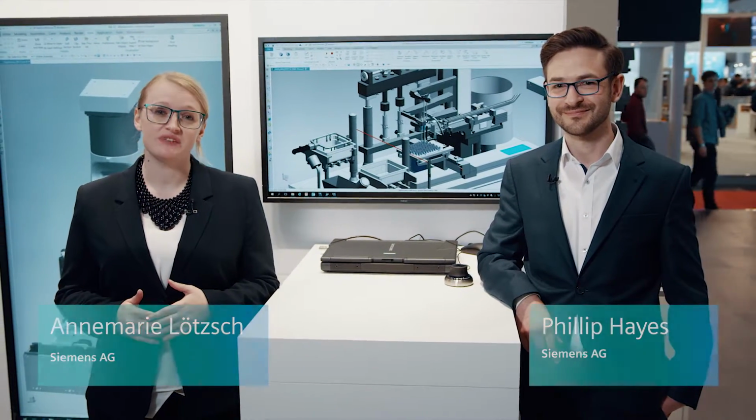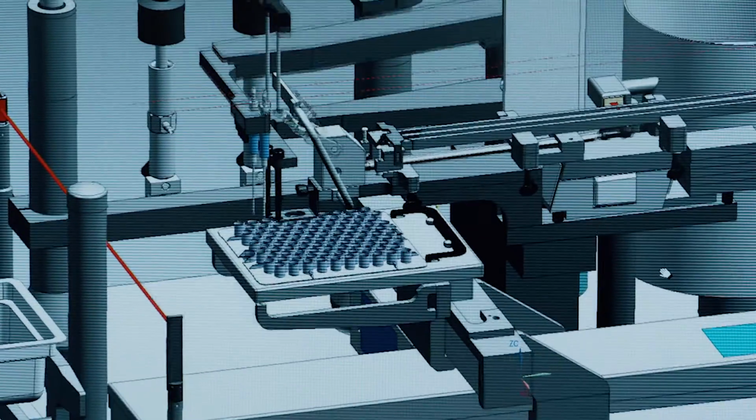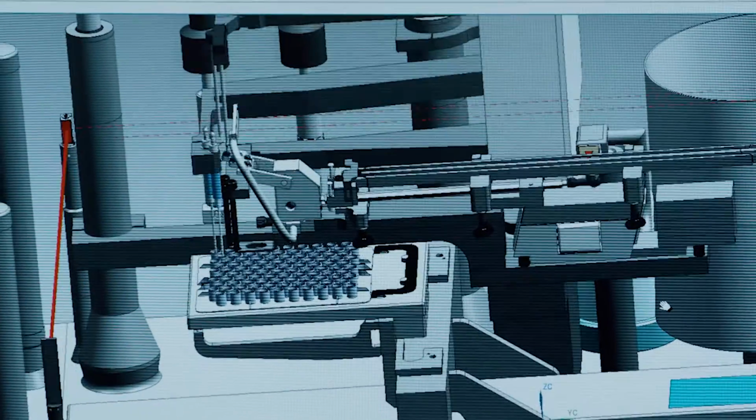To put production machines into operation faster, and at the same time to improve the engineering quality, virtual commissioning helps to achieve these goals. Like a real commissioning, the mechanics, electronics, and automation program of a machine are combined, tested, and validated, but instead of using real components, simulation models are used.